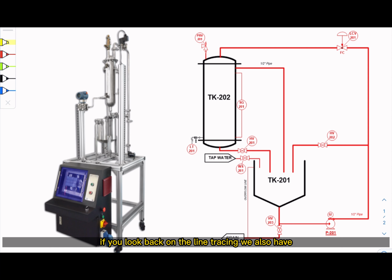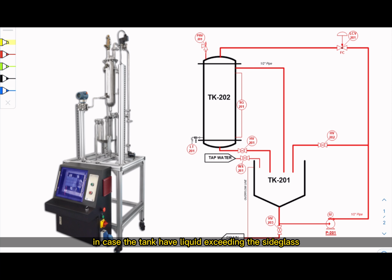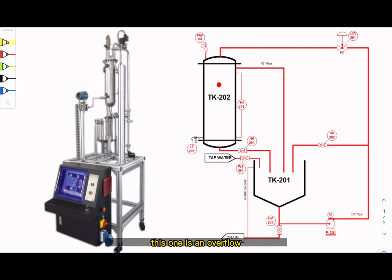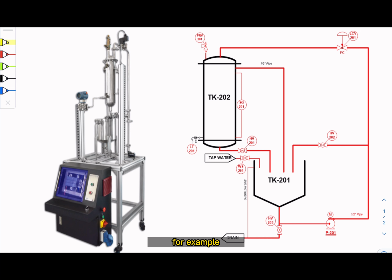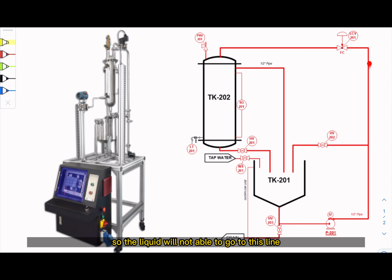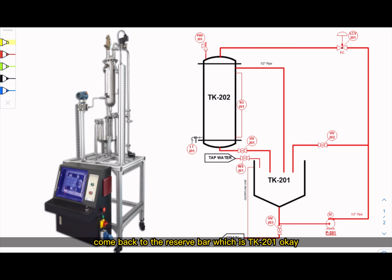If you look back at the line tracing, we also have this overflow, in case the tank has liquid exceeding the side glass. And then we have this bypass line. The bypass is in case the LCV is fully closed, for example. The liquid will not be able to go through this line because it is fully closed, so it will bypass and come back to the reservoir, which is TK201.